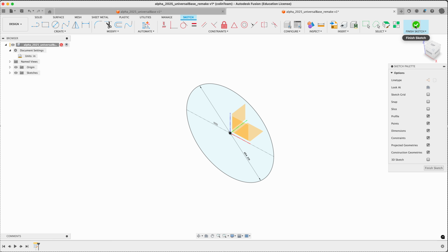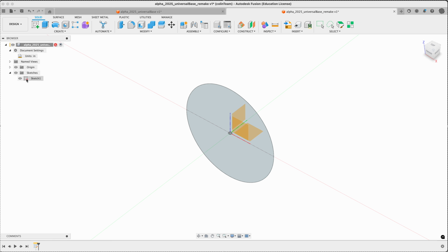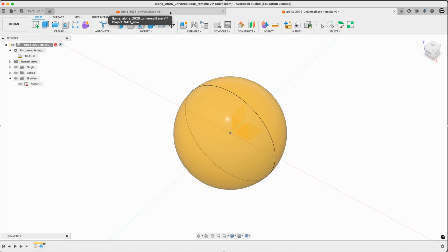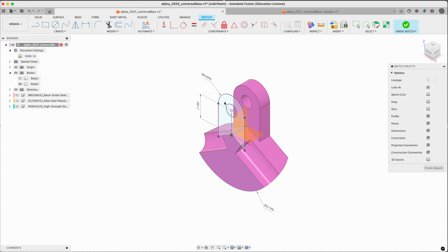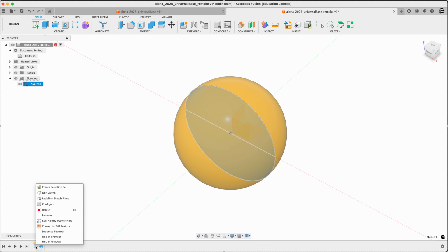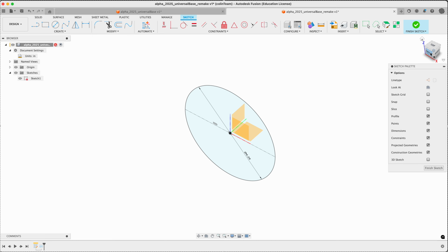I'm going to go ahead and do this in a typical loopy mode. So finish the sketch. Keep an eye on it, make sure it's always fully constrained. Good. And we'll do a revolve. That's our start. Now, if we're lucky, everything else is nestled within. Let's have a look at this. So inch up, 0.625 in radius. So let's go back to our sketch. We're only allowed one, right? So let's edit the sketch.